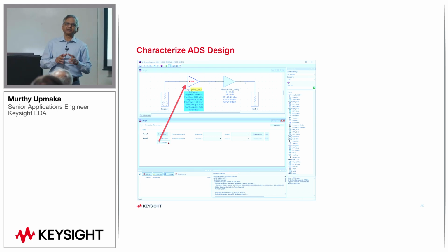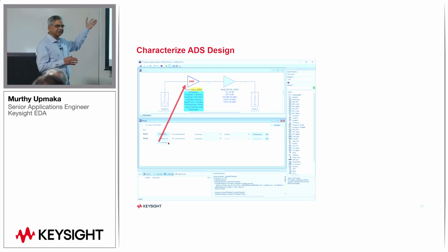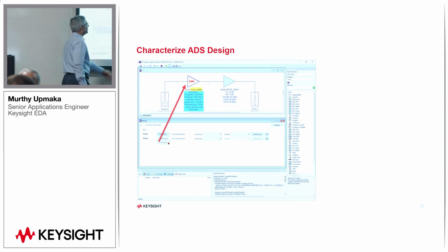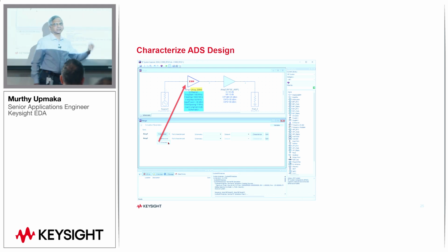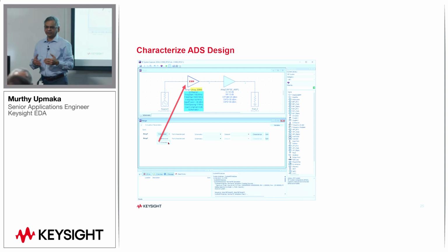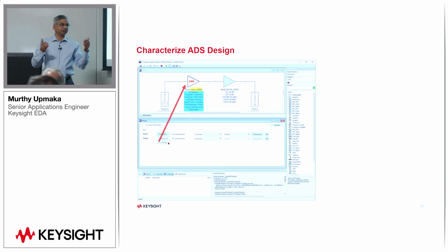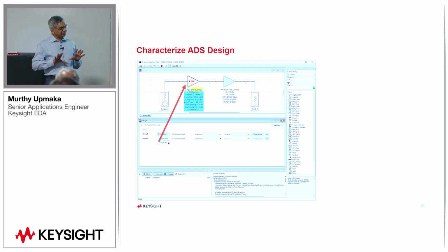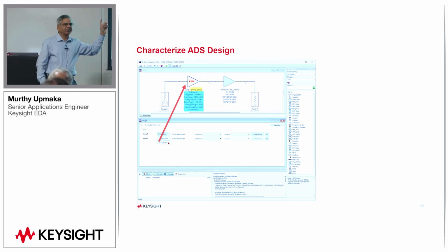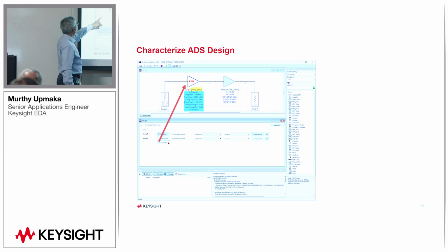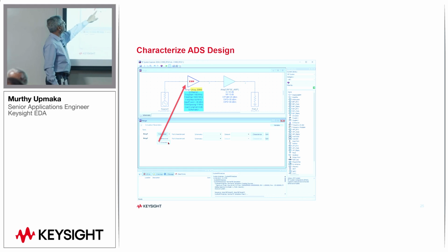initially we are providing some templates you can open. The template can be a simple amplifier, but you can add parts. The parts are here. You can add to whatever default comes, and then you can put them together. After you put together the chain in ADS, you're all still sitting in ADS, but this looks more like the other tool, the system view. And then at that point this UI opens, you can select the part and say extracted.